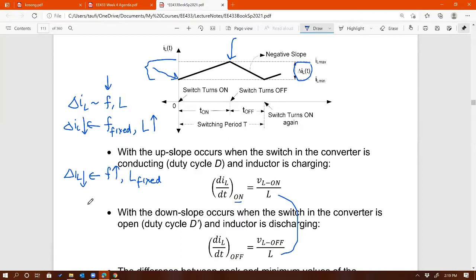And there are other things as well, such as, anybody from E410, 411 can answer. Besides the physical limitation of the switch, what else? Why can't we just keep increasing switching frequency? Come on. People who took 411 especially. Don't you also have a lot more heat dissipation if the frequency is higher? That's correct. So from where? The heat dissipation from where? Just from switching, so I guess for the FET itself. That's correct. Very good.